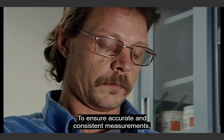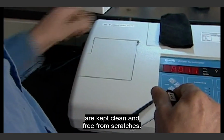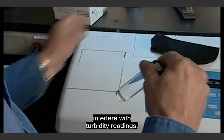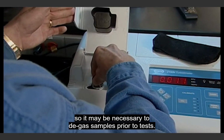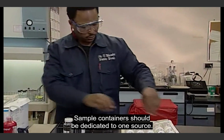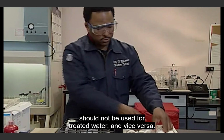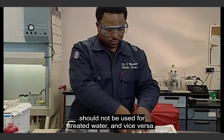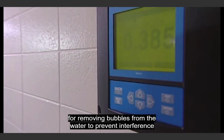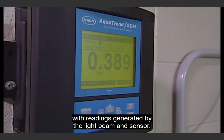To ensure accurate and consistent measurements, operators should ensure that sample containers and chambers are kept clean and free from scratches. Gas or bubbles in the sample will also interfere with turbidity readings, so it may be necessary to degas samples prior to tests. Sample containers should be dedicated to one source. For example, containers used for raw water should not be used for treated water and vice versa. Continuous flow turbidimeters have an automatic system for removing bubbles from the water to prevent interference with readings generated by the light beam and sensor.